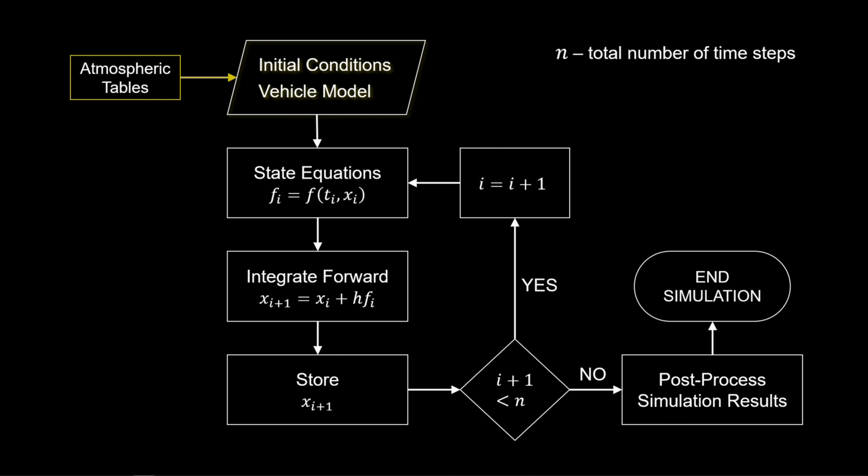This was stored as a bunch of column vectors, and then those data vectors were passed into the state equations as inputs and interpolated with a custom fastinterp function. The fast interpolator used linear interpolation to a single point, and if outside the data table, the last value was held constant. So this approach avoided any significant increase to total integration time.